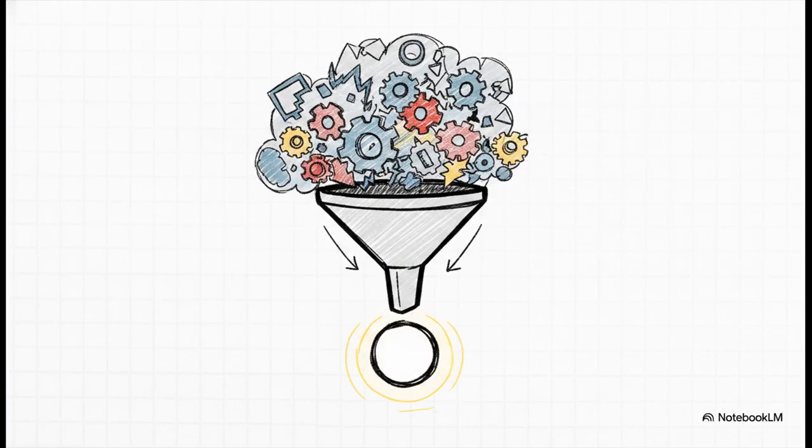Let's zoom in on that final step for a second, the base impedance. The formula is Z base equals V base squared divided by S base. Once this base impedance is established for a specific voltage zone, every single physical line, machine, and fault resistance in that zone simply divides its raw ohm value by this exact base. This process powerfully strips away all those incompatible raw ohms that were causing us so much trouble earlier.